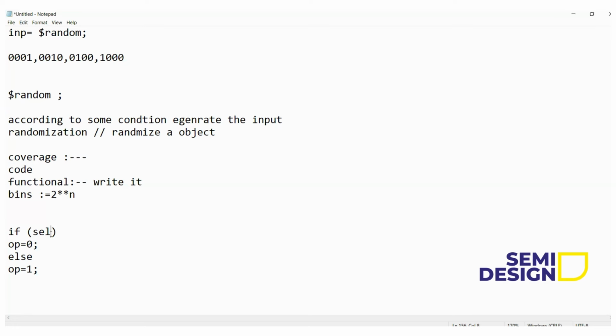So you will be the one who will be analyzing the code coverage. If code coverage is not 100%, the tool will show that these parts of the code are not getting executed. First you have to check whether you have generated those values or not. If you have generated them but it is still not getting executed, then inform the designer. The designer will inform you whether this is correct or not. You cannot do the changes. If it is dead code, the designer will remove it. In case of dead code, you will get less code coverage.